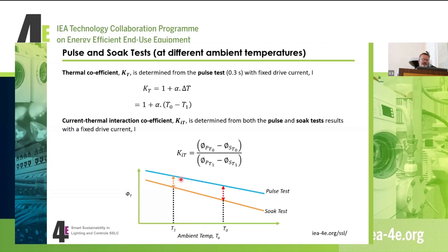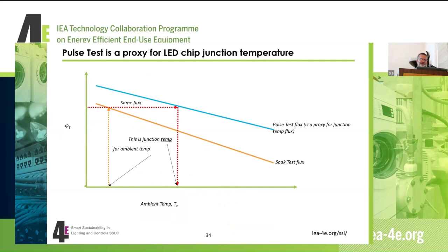And as you can see with a product, as we use a higher ambient temperature, this is the initial turn-on luminous flux, but most of the time there'll be a greater drop down to the stabilized luminous flux output down here, okay? Well, how does that help us?